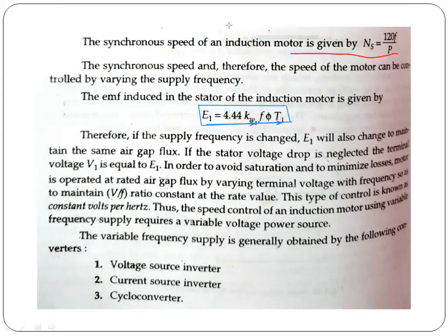So from here we can understand that if the supply frequency is changed, E1 will also have to change to maintain the same air gap flux.